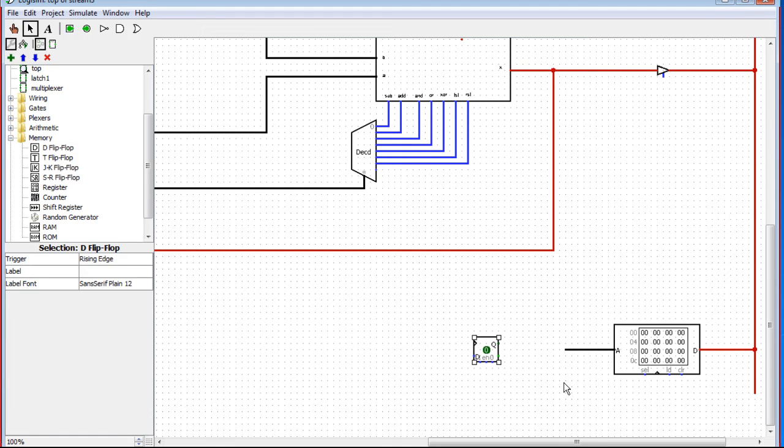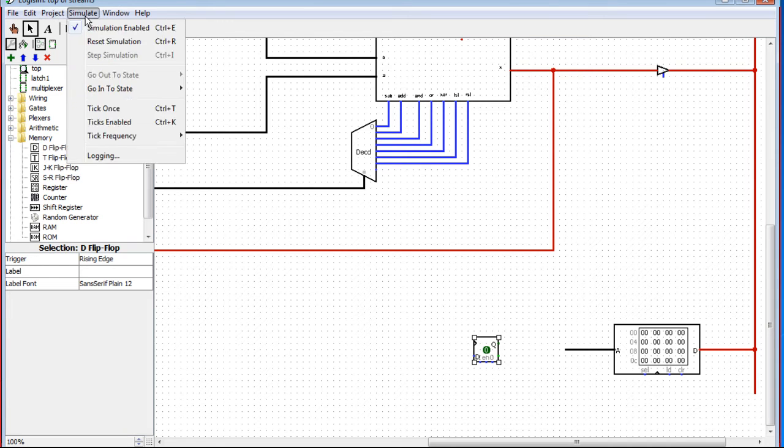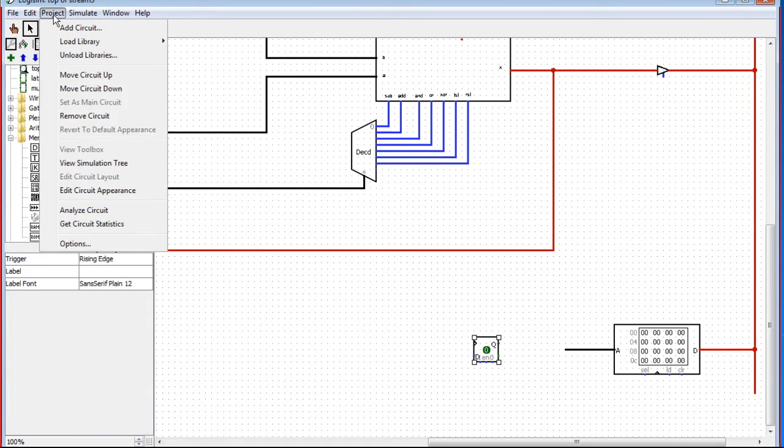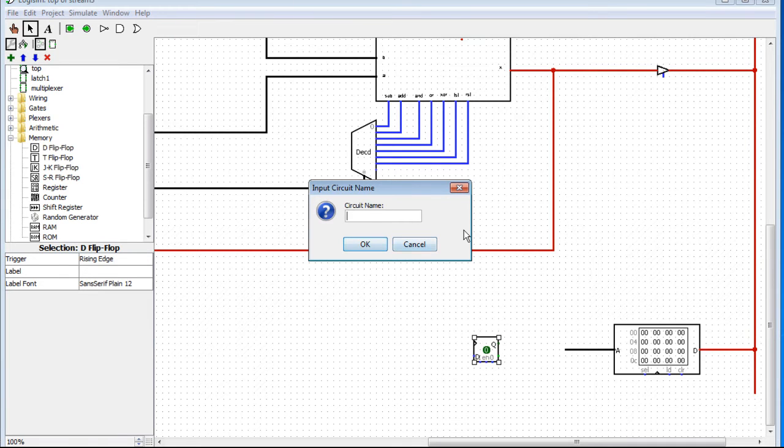It increments every instruction to load the new instruction, to point to the new one. And we don't want to have to increment this by passing it through the ALU, because that's going to be a pain in the ass. We can do it without passing it to the ALU, because you can create a register that is able to increment itself. It's called a counter. So we're going to make a binary counter. Make an add circuit. Counter.